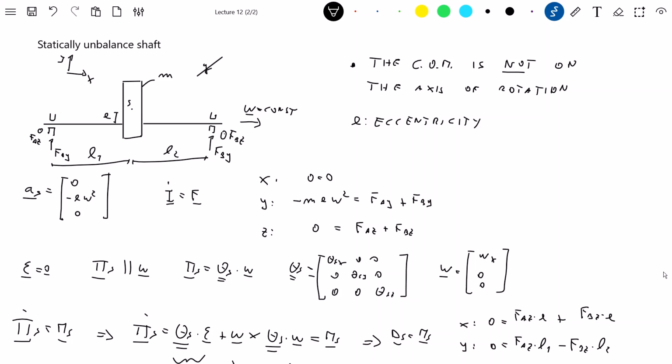And that's all the time, whatever the direction, we have a force at the hinge, at the support, which has to compensate this eccentricity. So with the direction of the eccentricity, we will have two radial forces on this support. And since this is rotating, these forces are also rotating. So imagine you have a force which is rotating, so it changes with time, and this will cause vibration, and it can even cause very heavy vibrations. So it is really a common engineering problem.